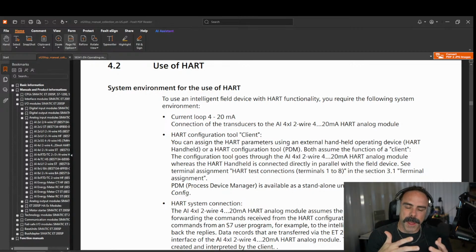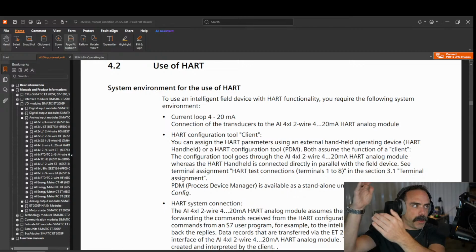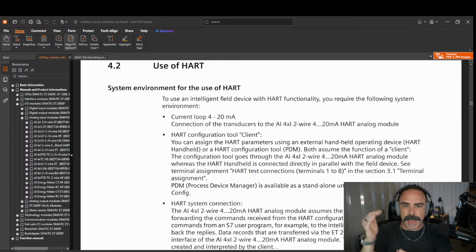So they give you the option to put 4 variables into your process image table and make them available as standard IO. All of the other data that is available in this HART module is available through data records. I'll probably go into this a little bit more later, but I had trouble choosing between the best way to create my block, the easiest configured way, because frankly, if you have these four addresses in your process image table, you could just put them in and use those.